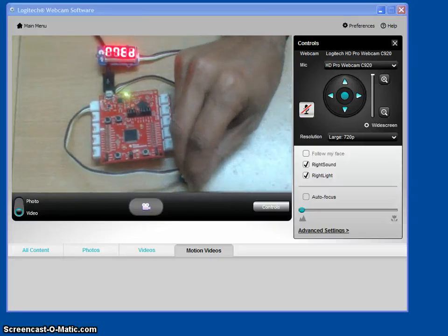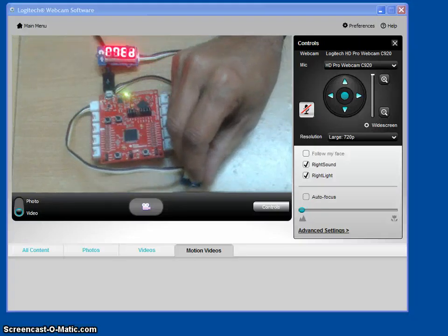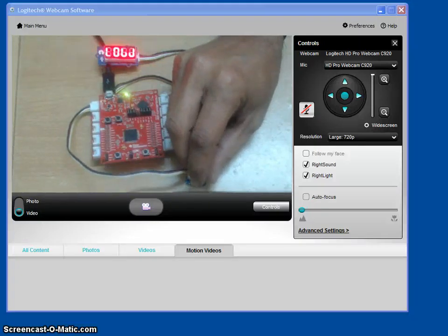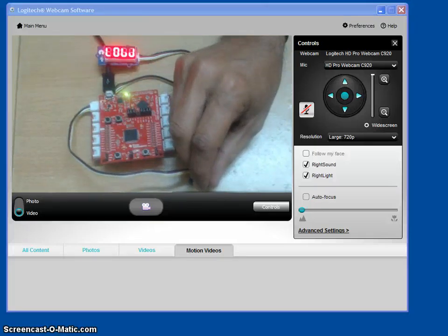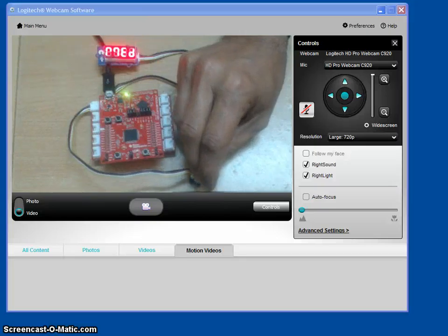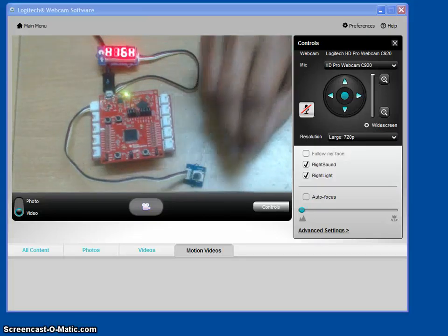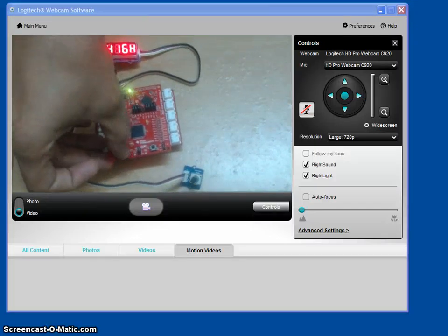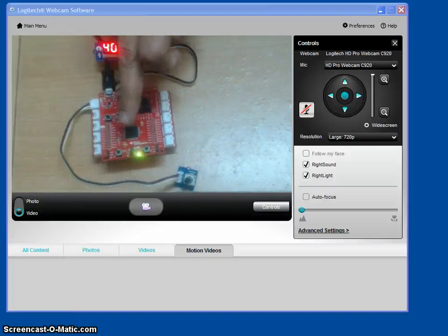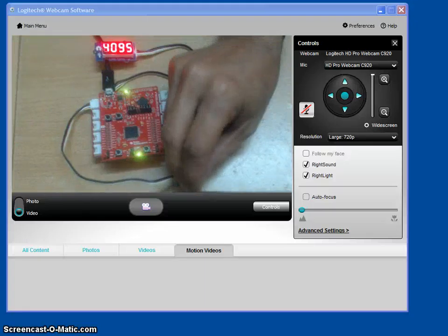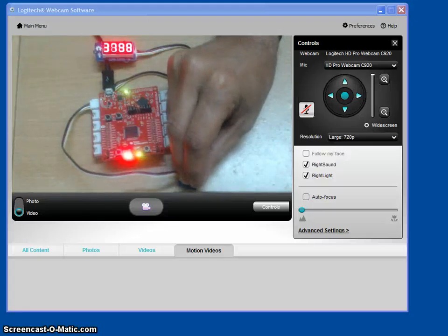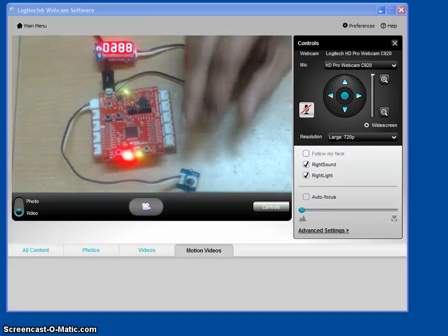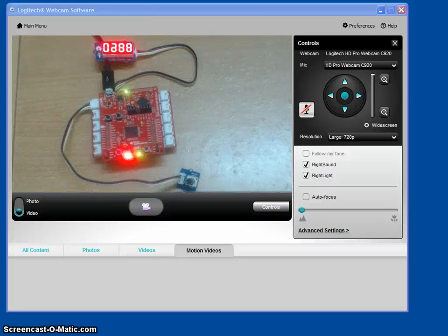So it is right now at high, and this is medium. So when I reduce it, it goes to low. So there are 3 statuses displayed on the 7-segment display: low, medium and high. Again, if you click on this, it will get back to the display value here. So again, if you change the potentiometer, it will show the status on the LED. This is a task which you have to implement in your coursework.